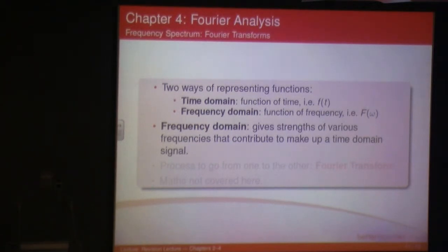Now we did this transformation with the Fourier series. Your coefficients an and bn will be the magnitude of the sine or the cosine of a certain frequency that go to make up your time domain signal. So if your time domain signal is a square wave or whatever, you've got an an or a bn term. Then you can plot your frequencies along the bottom, and you can have your values for an and bn at the certain discrete frequencies that you're using, and that will be a frequency domain spectrum.